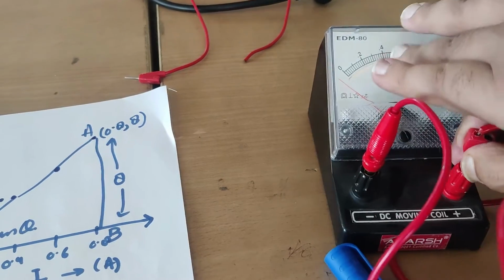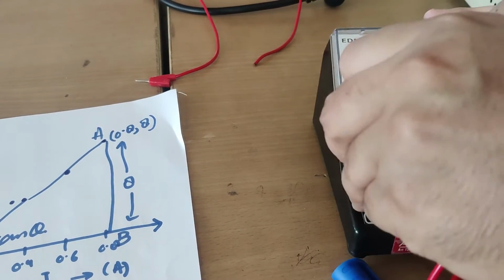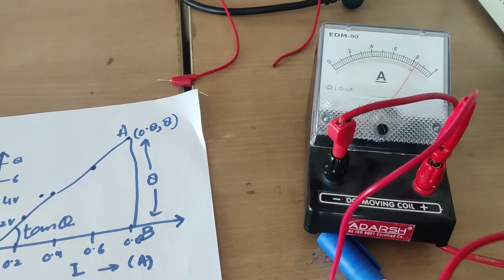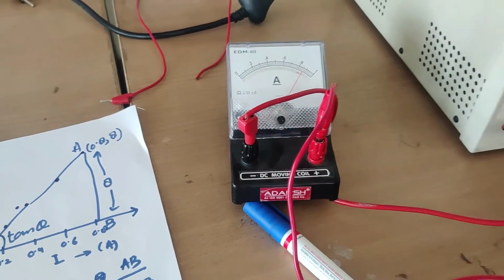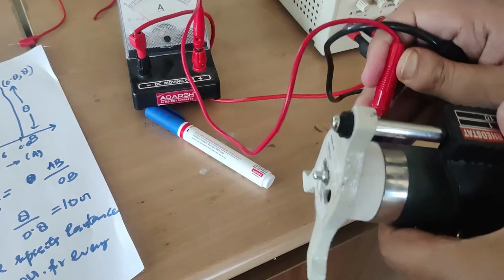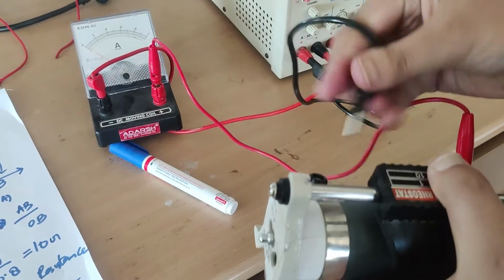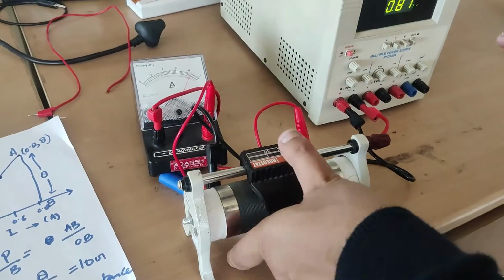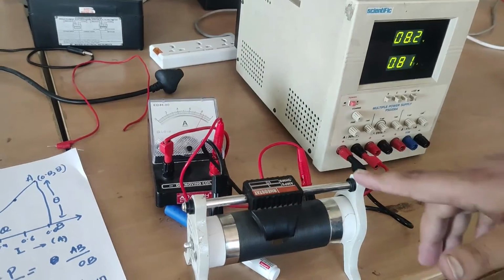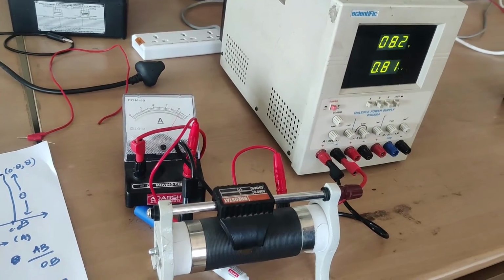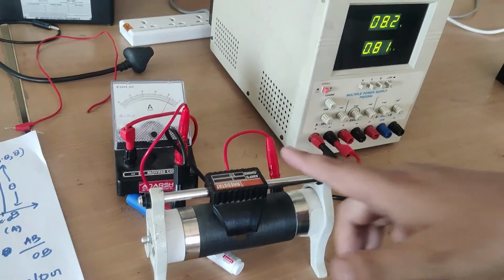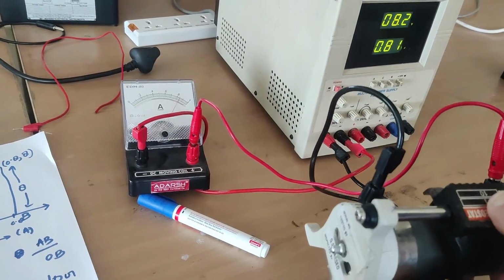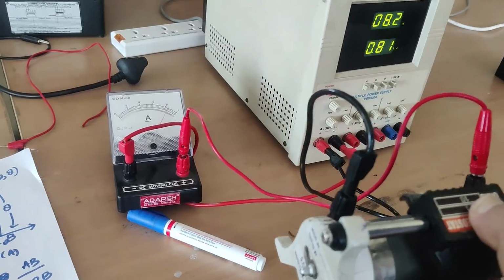Now if I interchange the connections on the ammeter, you can see the current will flow in the positive direction. Also, if I interchange the rheostat connections, you can see the current is flowing. That means this is a bidirectional device. Instead of this, the diode is a unidirectional device. I will also prove it in the next experiment. If we change the potential, you will see the current will flow in only one direction. Okay, thank you very much.